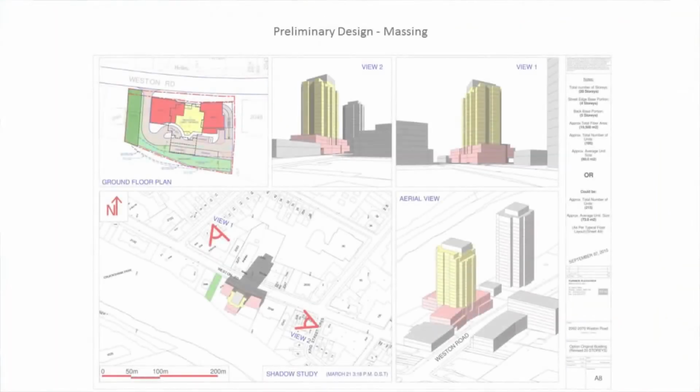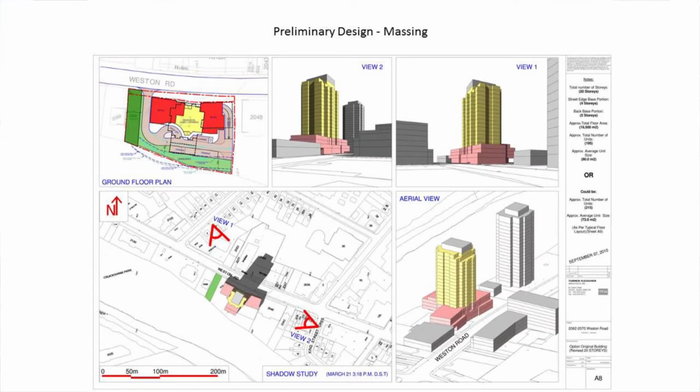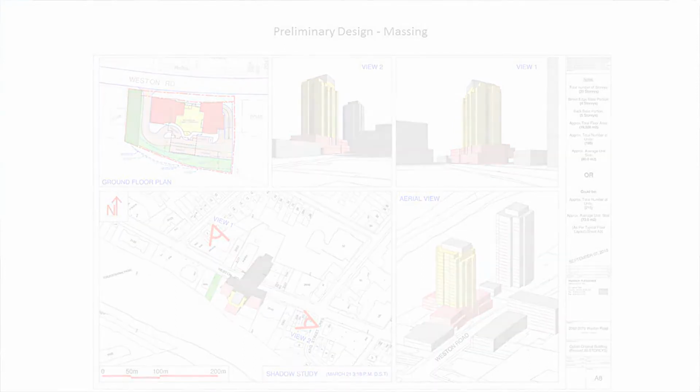So, how does that work? Yes? Sorry, what's massing? Massing is probably one of the first steps that you start with. So something like this, a client comes to you with a site, what can I build on? So you start looking at zoning, sort of what's allowed on that site, and then obviously you try and maximize. You want to maximize your return on investment. So this is probably one of the first things, saying, okay, I'm allowed a floor plate of 800 square meters. This is what I can do, and then you start sort of breaking it down. I can get 4 1-bedrooms, 4 2-bedrooms, and basically it's really just back and forth, seeing what the client can get the most bang for his buck.